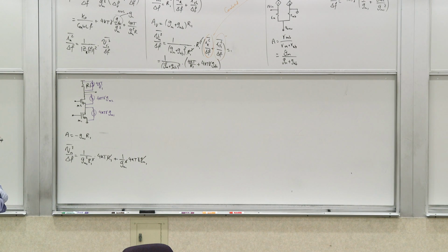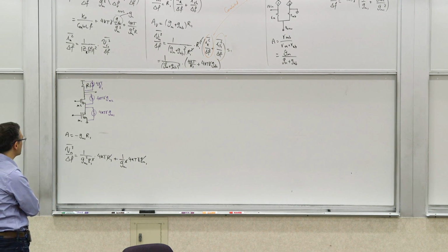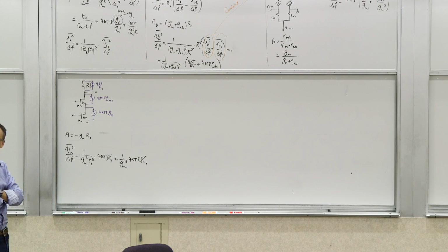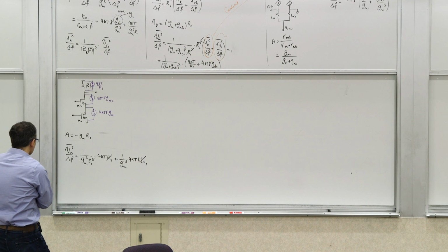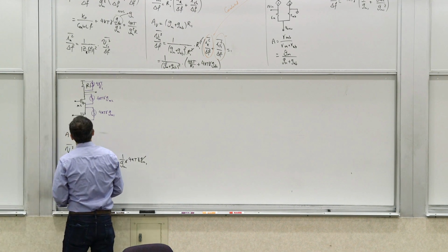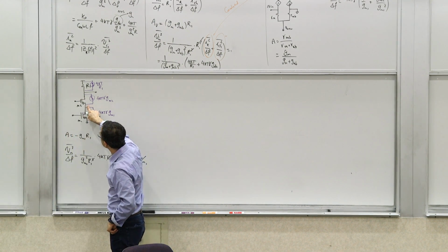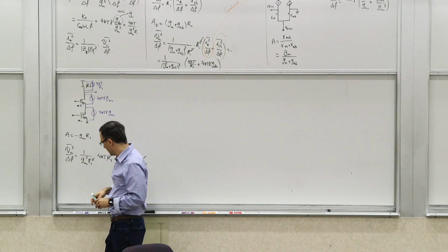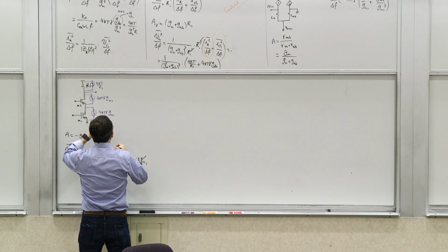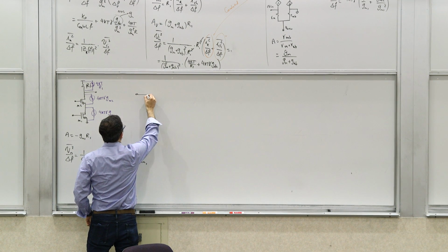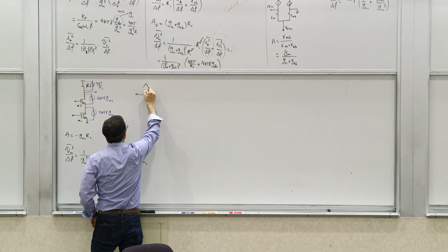Let me ask you another question. To understand the contribution of that thing to the input, you have to understand its contribution to the output. The output is the key to understanding what really happens to the noise. So what is its contribution? Think about it: how is this current divided here? Let's look at the small signal model for this guy, forgetting about the body effect.